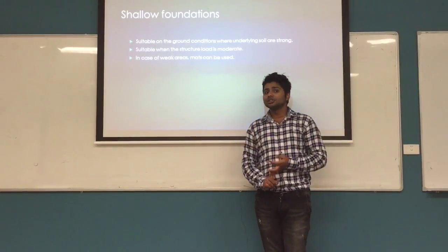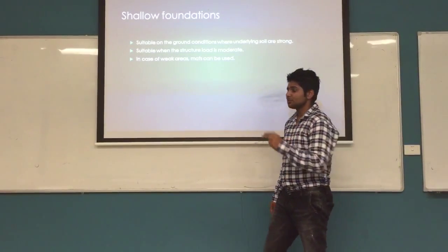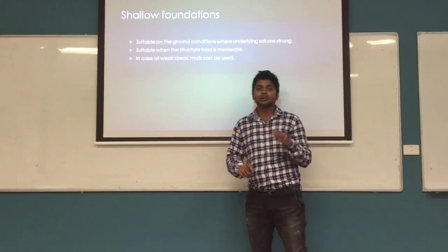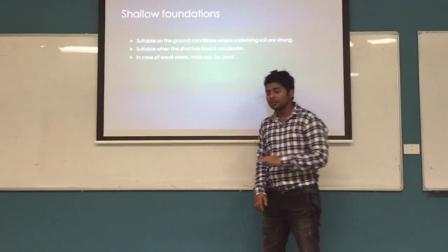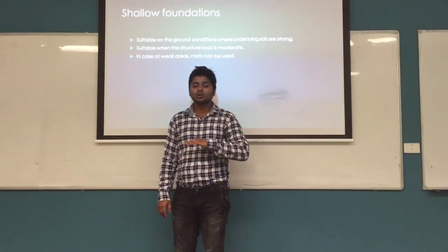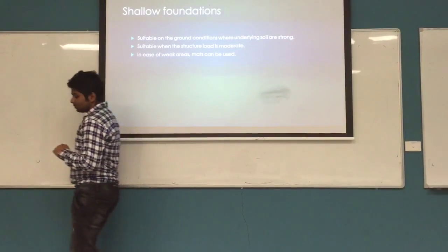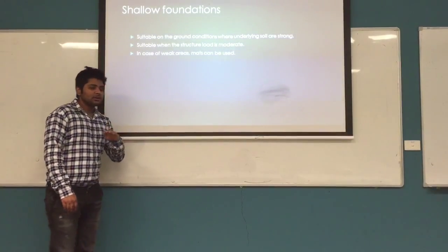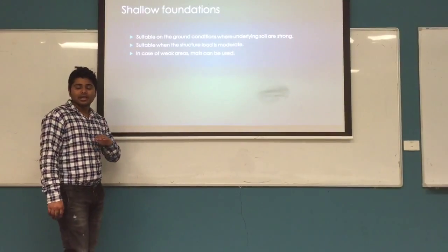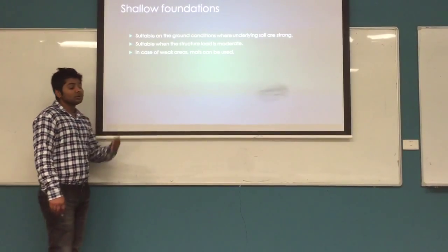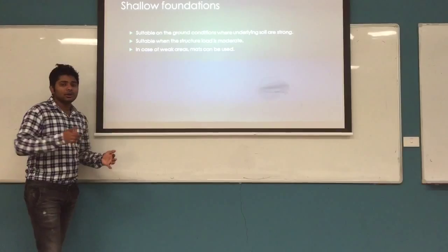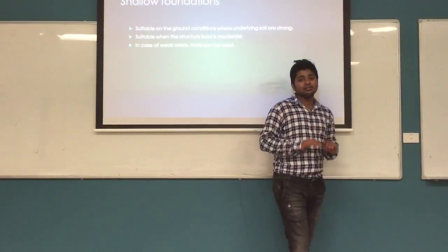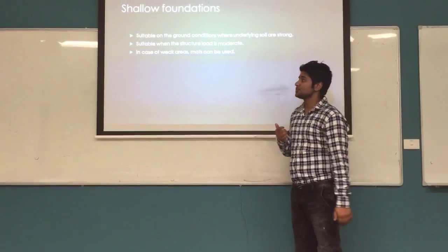Now let's come to the shallow foundations. Shallow foundation is adopted when the underlying soil is strong enough to hold the pressure or the load of the structure. Second, we adopt the shallow foundations when the load of the structure is moderate. When we identify weak soil at a shallow depth, then the mat footing is generally used.